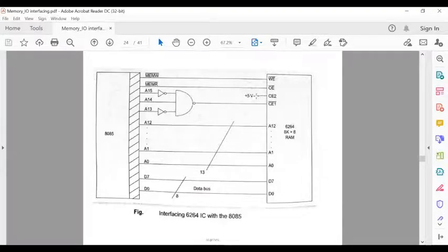So that is to be connected with the 5-volt power supply, where logic 1 is available every time. Now there are two control signals that need to be connected with the microprocessor. Two control signals are generated from the memory read and the memory write. With the help of these three signals, IO/M bar, read bar, and write bar, and assume these three signals are already fed into such a circuit that the circuit output must be connected to the control pin of this RAM IC.